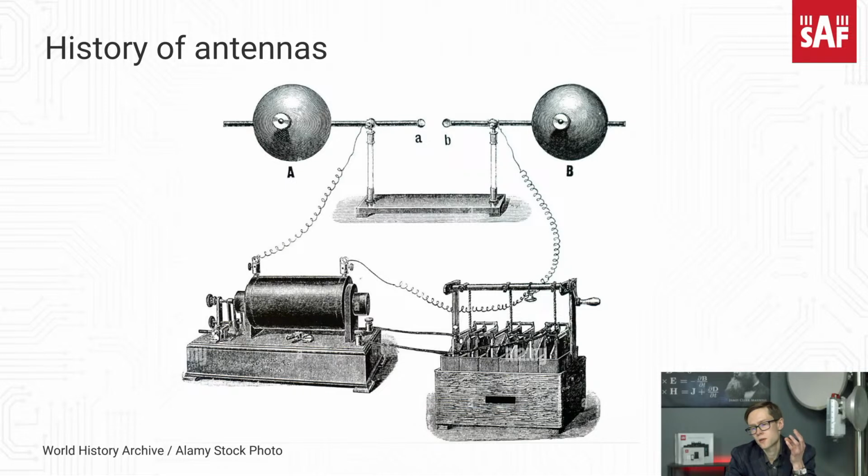So it consisted of a capacitance-loaded dipole resonator consisting of a pair of 1 meter copper wires with a 7.5 millimeter spark gap between, and ending in 30 centimeter zinc spheres. So when this induction coil applied a high voltage between the two sides, there were sparks across this gap which created standing waves.